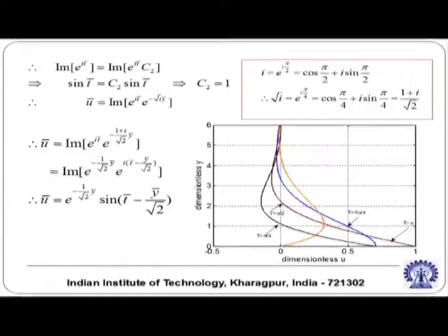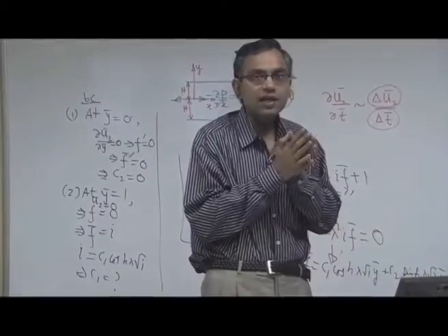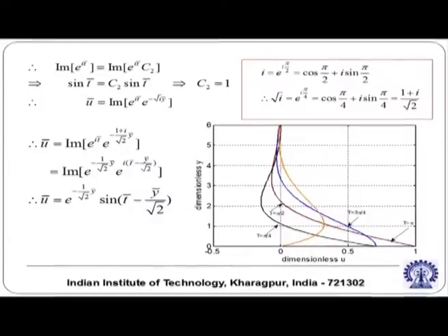The typical dimensionless times which are plotted are pi by 4, pi by 2, 3 pi by 4 and so on. I will advise you to plot at other intermediate dimensionless times and figure out how the solution is progressing as a combined spatiotemporal characteristic of position and time.